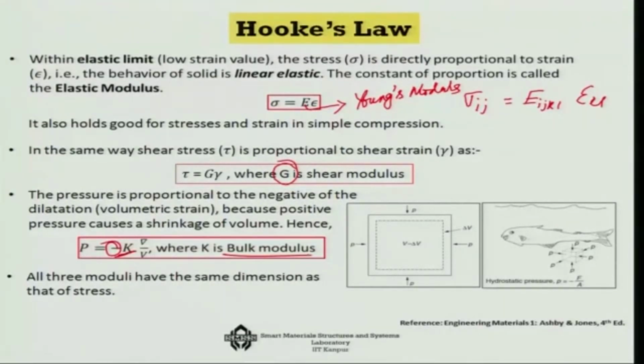So, we have 3 different moduli: the elastic modulus in the first case, which is Young's modulus, shear modulus and bulk modulus. All 3 moduli, however, have the same unit as the unit of stress, because strain is unitless. Okay. So, that is about Hooke's law.